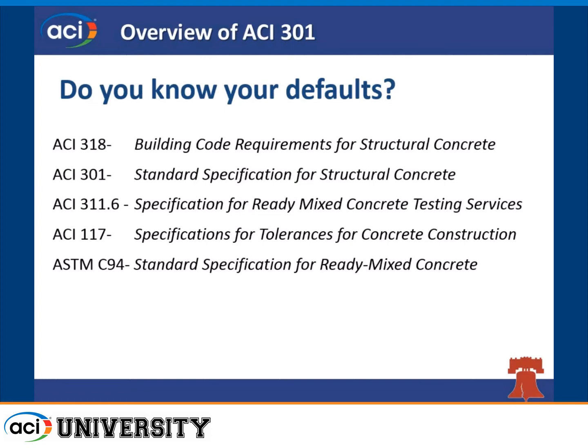There are other specifications we use within 301, such as 117. We use C94, which is the standard spec for ready-mix concrete. We also lean on a few others outside of our areas of expertise, such as the Post-Tensioning Institute has a guide on materials and on construction and design. And then we have also leaned on the Concrete Reinforcing Steel Institute for their epoxy certification. There's some other examples. So we can lean on other industry guides as long as they are in mandatory language. If they're not in mandatory language, they do not have a place in our document. We cannot reference guides that are in ACI. It has to be in thou shalt.